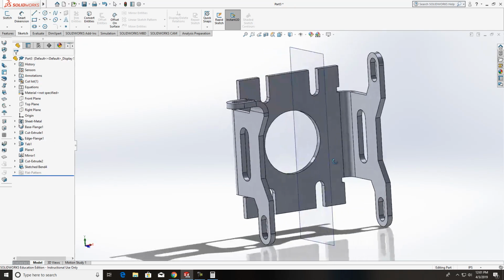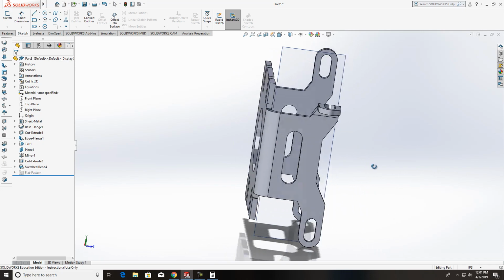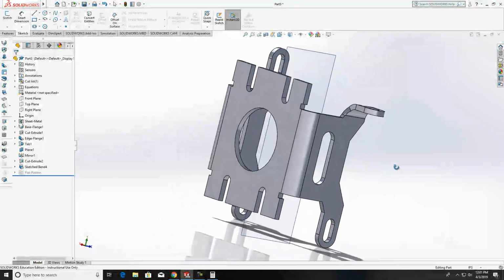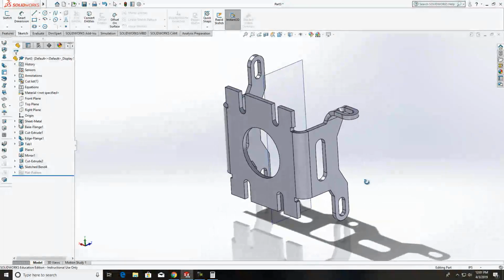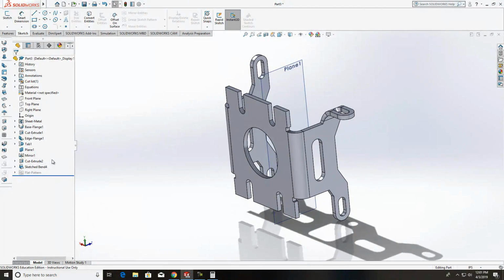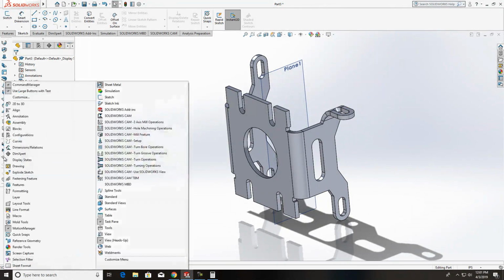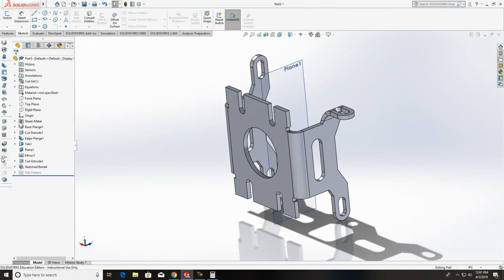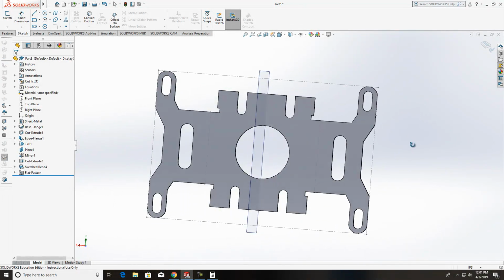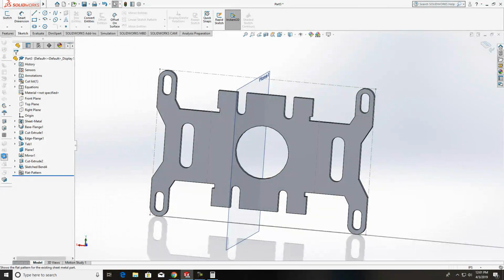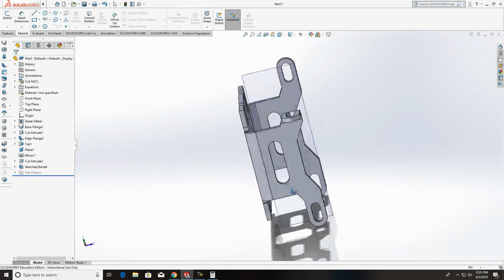So there you've got that bent, and for the rest of the way out, you can look through your tutorial, but you basically got it. You're going to put it on a sheet. But one cool thing about this is you can actually look at the flat pattern. Right down here, if you scroll down, right here's a flat pattern. If I click on that, just regular click on that, it will flat pattern this for you. And this is what it would have to be stamped like. And then you can click on it again, and it'll take it right back to the bend.